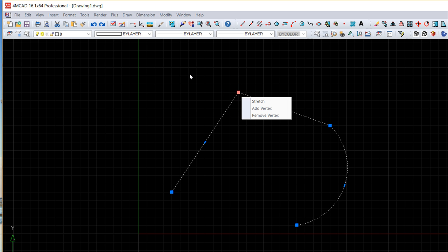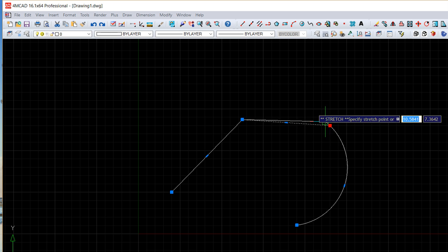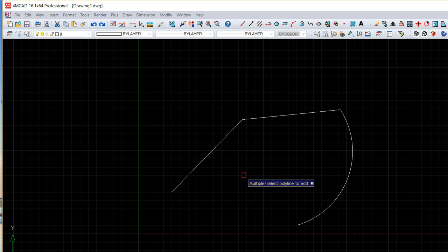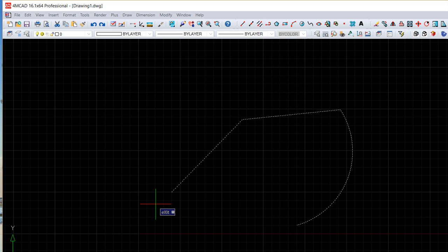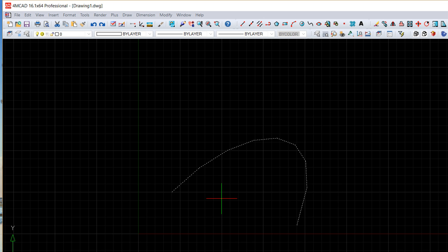So now with the polyline created, I can, for example, change the vertex. I can call the entity and do the addition of vertices. I can do the close, for example, C, okay, and it will close the polyline. I can do a fit, F, okay, and the fit will make an approximation curve that takes into consideration the control points. I can reverse the polyline. I can create a spline, which is a little different from the fit.